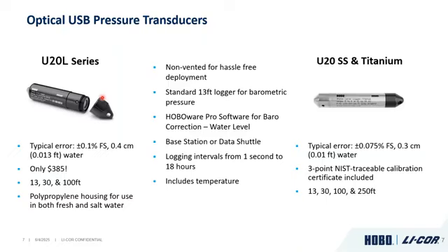These are data loggers. They're meant to be left out in the field. They're rugged and reliable, and these loggers will allow you to log anywhere from 1 second to 18 hours, and you can leave them there. If you're doing 5-minute or 15-minute intervals, you can leave them there for months at a time. There's very little drift with these pressure sensors. It's a ceramic sensor, so it's very durable. So they'll last, and you can leave them out for months and collect that data later.